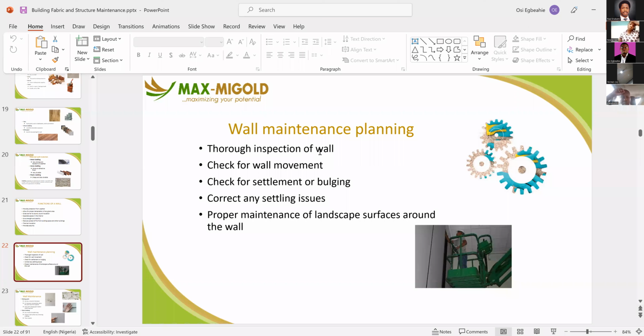But you also have the surface cracks that just happen due to either the plaster sand that was used for plastering or rendering the walls, or the building trying to get its own expansion joint, because every building should have a little bit of expansion joint, especially buildings that span beyond 30 meters.